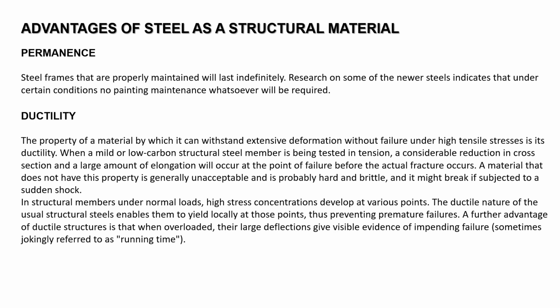We need to understand that ductility means the material will undergo extensive deformation before failure under high tensile stress, the cross section will be reduced, and a large amount of elongation can be noticed. This ductile behavior is desirable because it gives visible evidence, through large deflections, that an impending failure is going to happen.